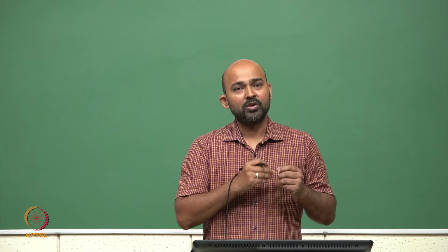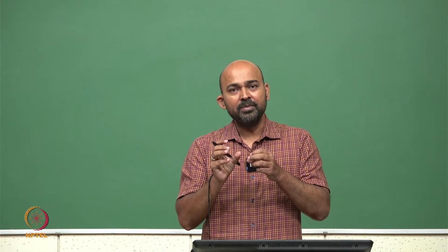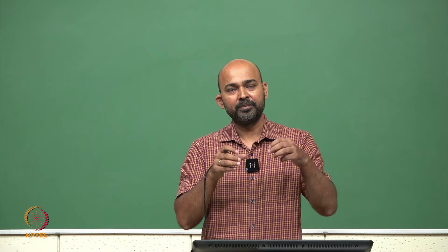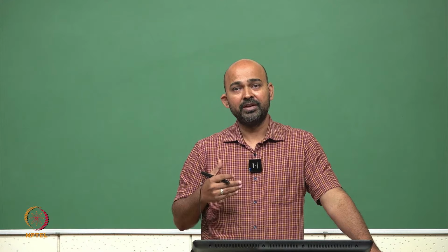In RF electromagnetic designs, you can study what a stub is actually called. So this stub actually comes in when we put a via to connect two conductors. This extra amount of length acts like a stub and we call it the via stub. So let's discuss what a via stub is.